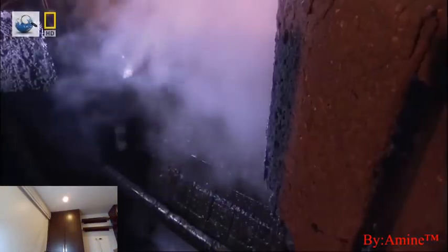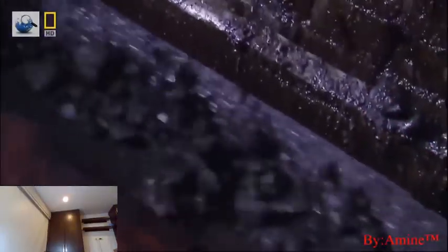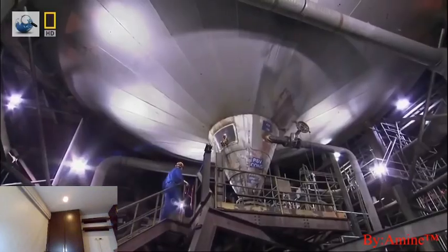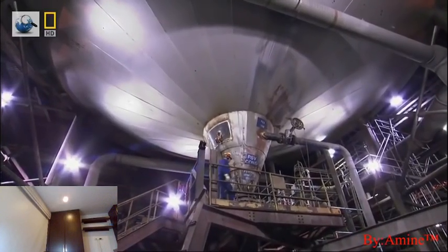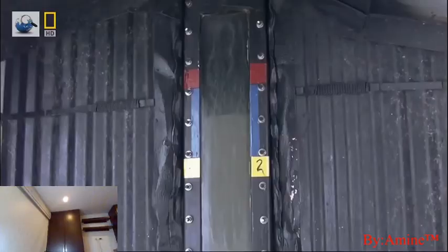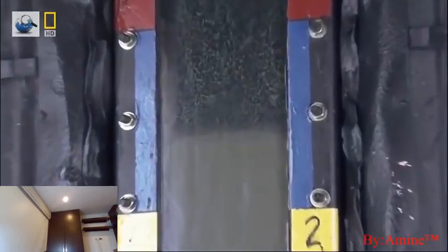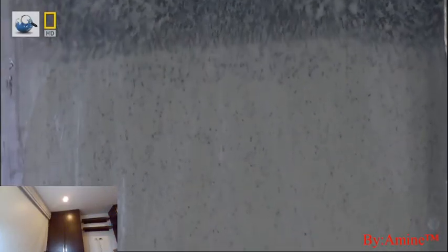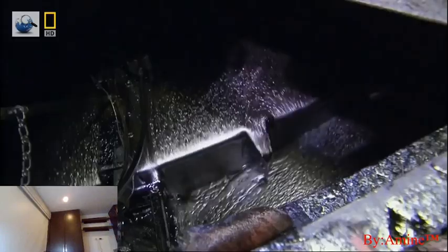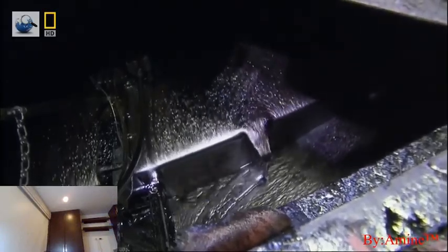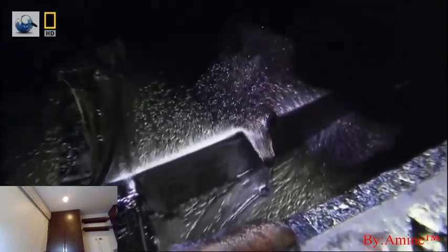First, the machines shake out the largest of the rocks, violently. With the big stones out and some hot water in, the mix flows into these huge basins called separation vessels. More hot water enters the mix, and as if it were the world's biggest salad dressing, the oil, globules of bitumen tar, separates and rises to the top. With a consistency of molasses, the bitumen froth empties out into collection vessels.